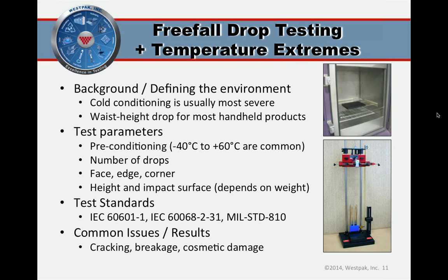Herb? Thanks, Mike. The testing terminology, as you mentioned, tends to cause problems in this particular area because the word impact can mean a number of different things. Previously, we talked about the impact testing plus temperature to mean the product itself is impacted with a rigid surface such as a steel ball, or what I call the catcher test. The reality of a product in use means that the product itself can also be dropped or impacted against a rigid surface. To avoid confusion between the two, that's why we decided to call this the drop test.